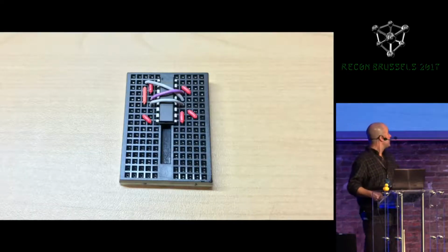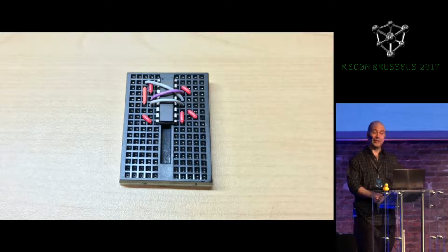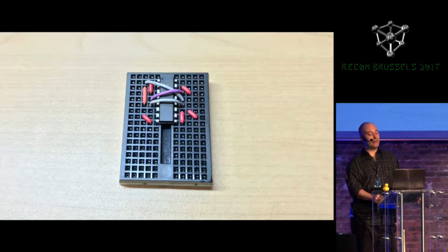So this is the actual circuit with the MAX 4619. This is basically the whole glitcher board, minus the XMega that I use as a microcontroller. I like the solderless breadboards. They're very convenient to work on. They allow you to change your ideas very quickly and test different things out. Any problems with high-frequency noise or anything like that, really for most of the projects that I do, I don't notice too much of a problem with it. I'm able to ignore it and kind of do things the cheap and easy way. So I enjoy that I'm able to just pop a chip into the breadboard, connect these wires, and in a few minutes I've built a glitcher like this.